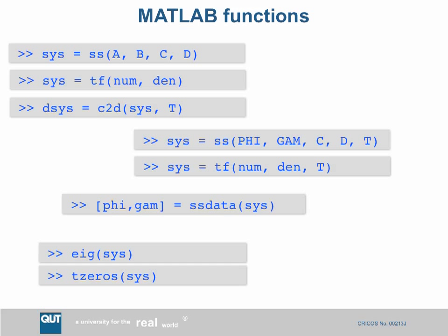It's really pretty straightforward. In a typical control design scenario, you choose some poles, you simulate it, you look at the step response, see if it looks reasonable, move the poles a little bit, generate a new pole placement controller, simulate it again, and typically in control design, you go round and round this design loop until you get a response that looks somewhat reasonable.